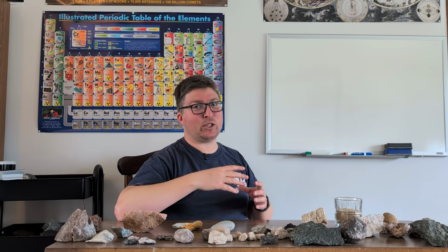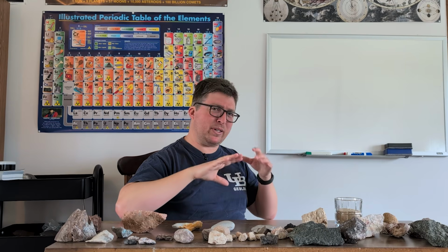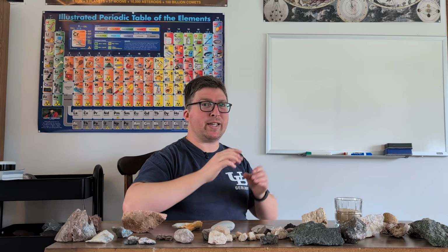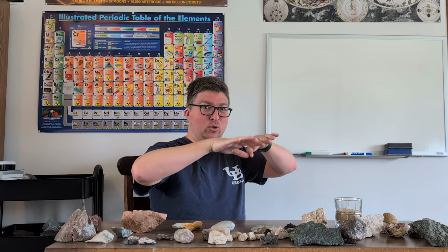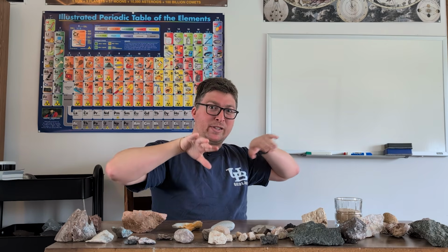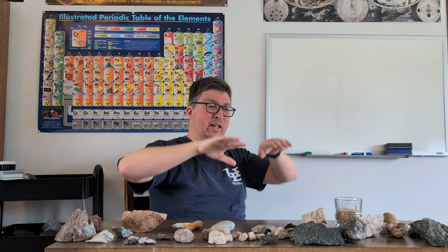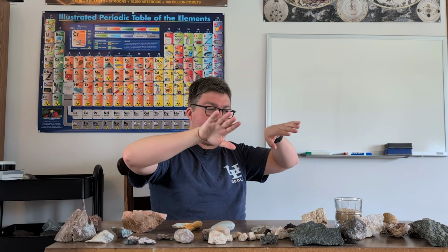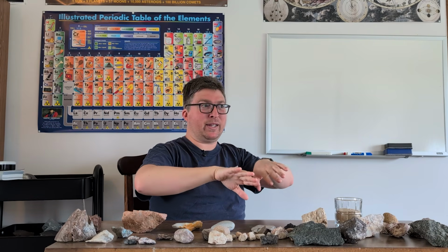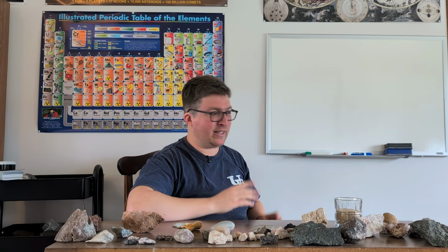Now, drawing water from a well does impact the water table and the groundwater flow around that well. And it does so in a fairly predictable way. Again, going back to our Slurpee, if you have a very slushy Slurpee, pretty well melted, not fully melted, but very slushy, you may notice that as you're drinking it, the area around the straw drops down while the stuff along the edges stays up a little bit higher. And as you drink it down further and further, it's going to slope steeper and steeper down into it as it flows in towards the straw. A well does the exact same thing.